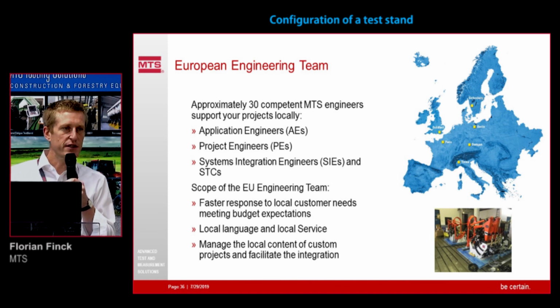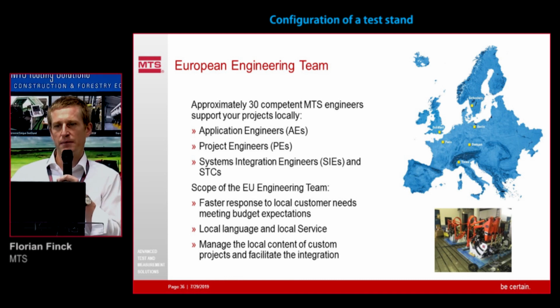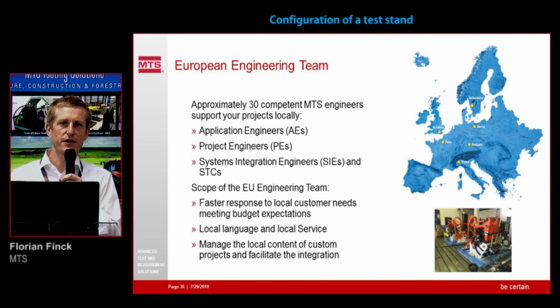And then there's questions that, of course, might require some expertise. So about the sizing of accumulation, the hydraulic setup of a system, the way how to mount the specimen in a fixture, and how to mount this test system on the strong floor or on a bed plate. That's something where MTS can certainly help.